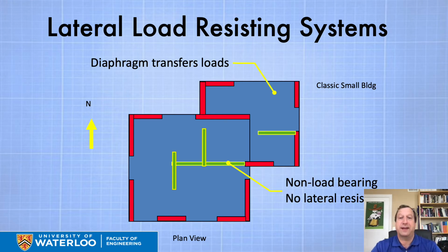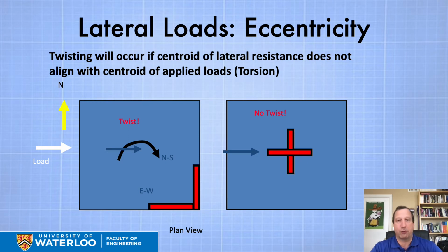On the other hand, if this were a 5-story wood frame residential building, then it would be challenging because the loads would have grown enough that there may not be enough strength shown in the red lateral resisting systems, and they would need some additional lateral resisting systems like braces or something like that.